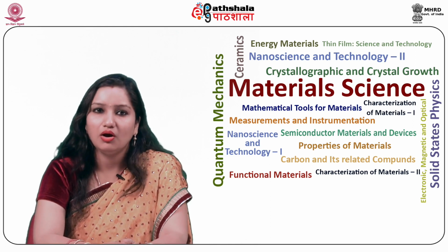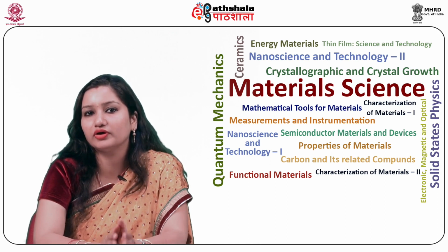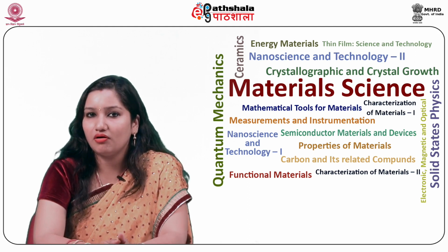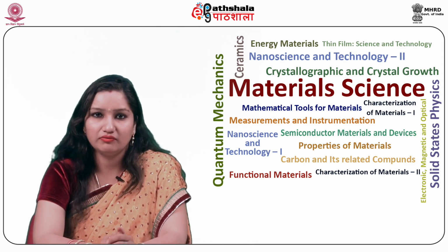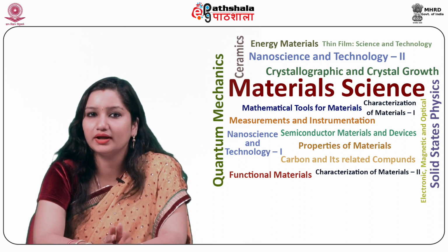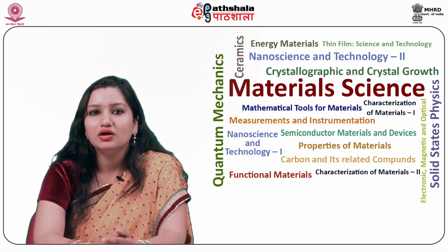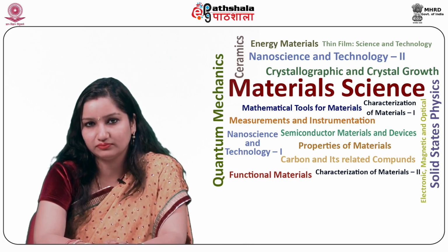The observation of photovoltage larger than the band gap in thin films of bismuth ferrite led to the renaissance of research in photovoltaic ferroelectric materials. An open circuit voltage of about 20 volts was reported for bismuth ferrite thin film, which has a band gap of 2.67 electron volts. It was further shown that the photovoltage could be enhanced or reversed by controlling the ferroelectric polarization, which is in turn controlled by electrical poling in lead-based thin films.